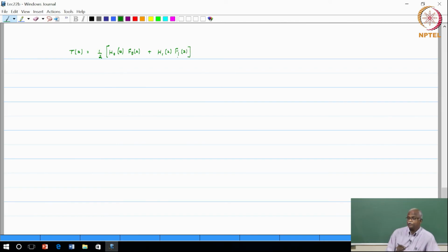This is my transfer function. Now, the thought process is that, okay, magnitude distortion we tried to eliminate, we went so far, it seems to be a little bit complicated. We split it into polyphase components. We said that okay, maybe the indication is to go towards IIR. So now let us try the other side.